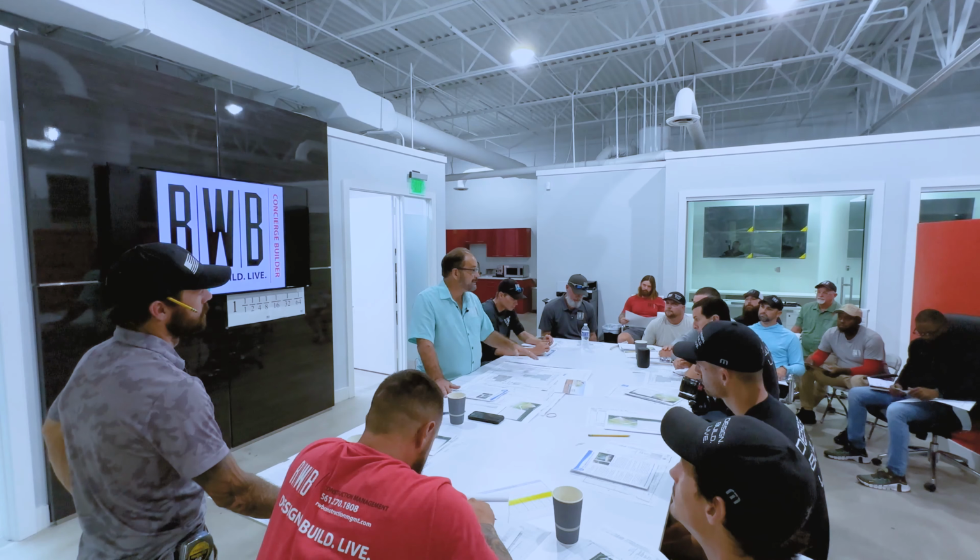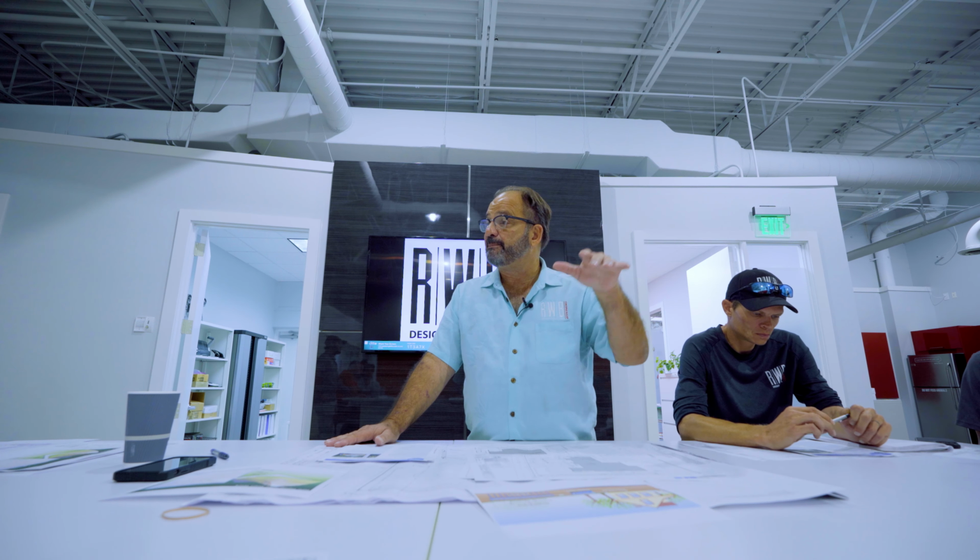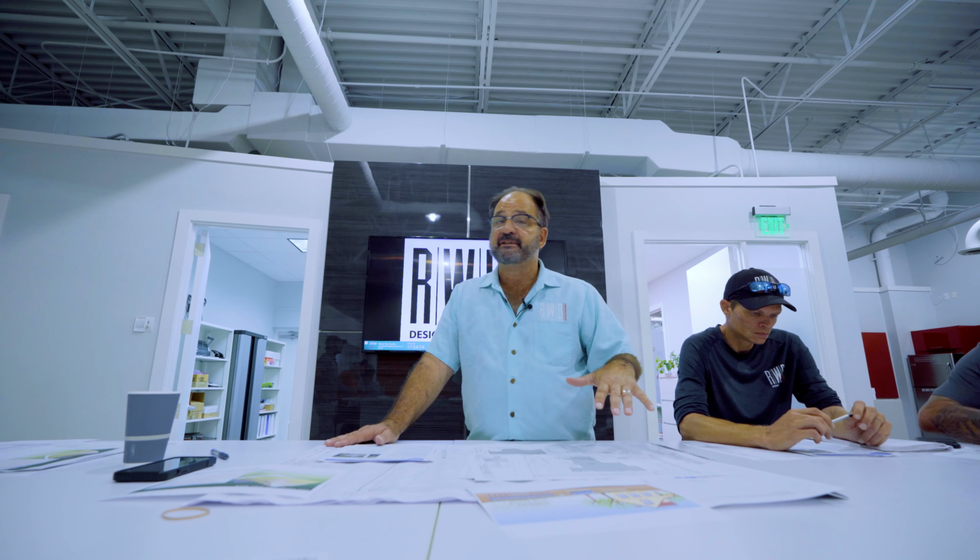Just like inside we had a benchmark that everybody was working off as far as putting outlets up or down or ceiling heights or cabinets. Outside you have the survey mark. That mark has to be maintained for everything, or you're going to have a problem because the first floor here is going to be different than the first floor here. Okay? Anybody got any questions?